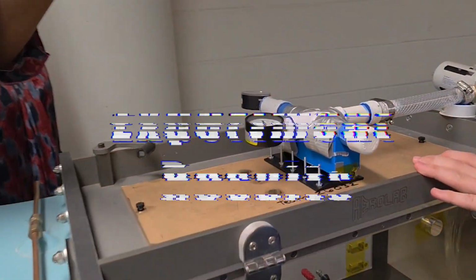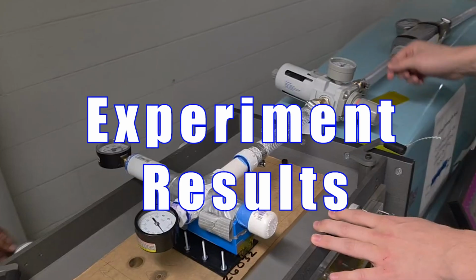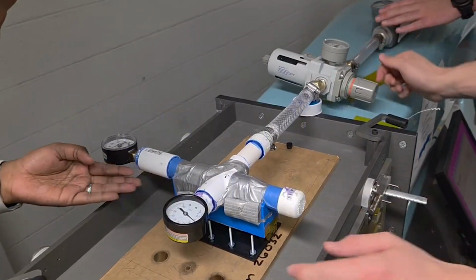Our experimental test results validated that the Coanda-driven geometries successfully controlled the flow of the leakage injection air. Throughout each test, the mass flow rate of the secondary flow system maintained the requirement of 2 to 3% of the free stream mass flow rate.